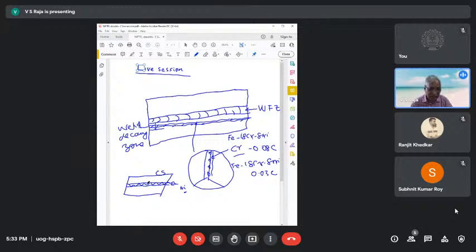Yes, there is a possibility of the filler wire being anodic compared to the base metal. Yes, there is a possibility of galvanic corrosion because of that. Yes, there is a possibility of improper fusion that has led to corrosion of this. Corrosion, wear and tear all can happen. Yes, there is a possibility of what is called microbial corrosion taking place. So all these possibilities one can examine by taking a cut piece of this and trying to examine various parts of it, so that you get a clear idea why it is really happening.